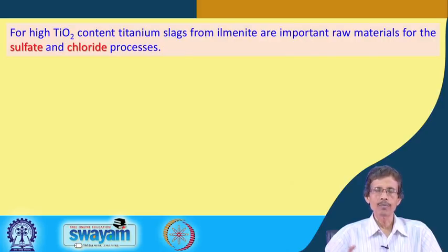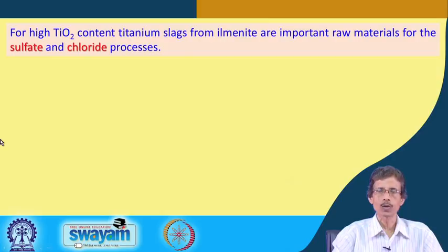But if we are careful enough to get that slag and process it for the corresponding titanium dioxide pigment, that will be very useful. So, we can use two inorganic chemistry based or solution based techniques which will be useful to get back that titanium we are throwing away as slag material, for getting titanium dioxide white pigment through the processes which are the sulphate process and another is the chloride process.